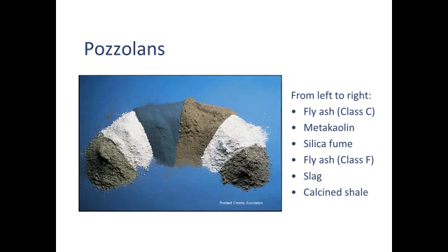So the color of the pozzolan when you're holding it in your hand isn't representative of the color of the pozzolan after it's done reacting. Now, fly ash and silica fume, that dark bluish gray one, those colors are preserved. You still see that. Slag is kind of whitish. VCAS is also whitish. I've seen VCAS be kind of grayish, and there are some other recycled glass derived pozzolans that tend to be a little bit of a creamy brown because they have a lot of brown bottles in them.